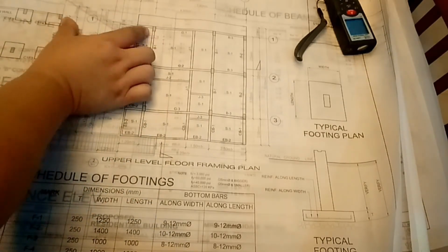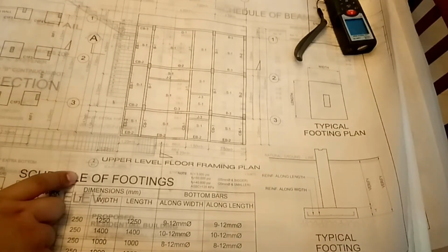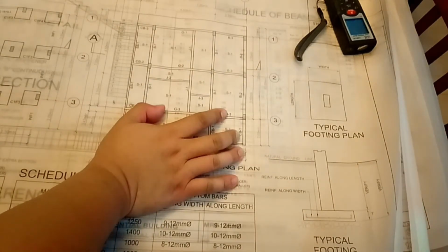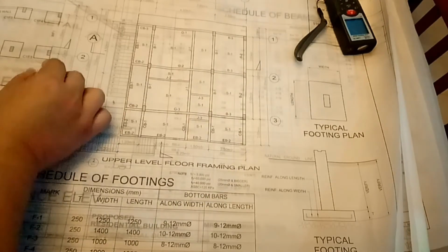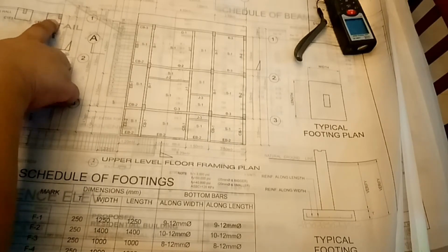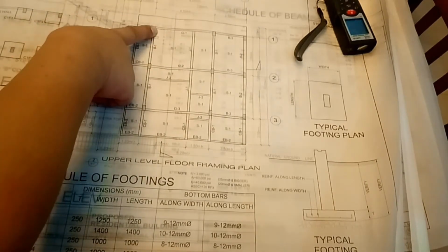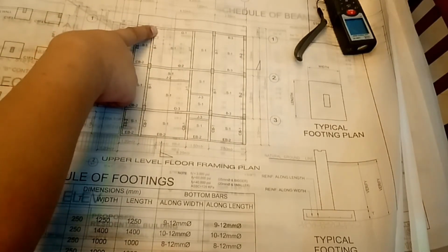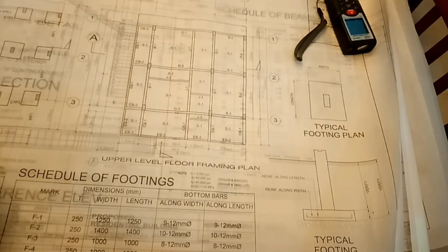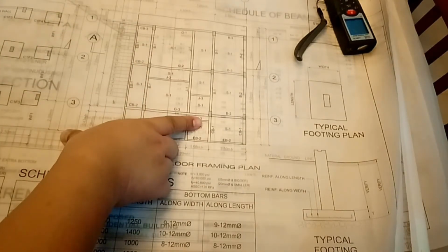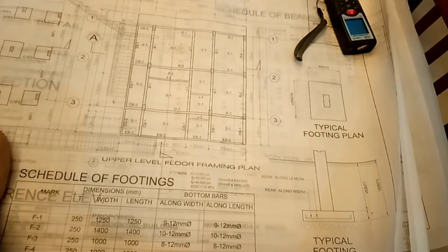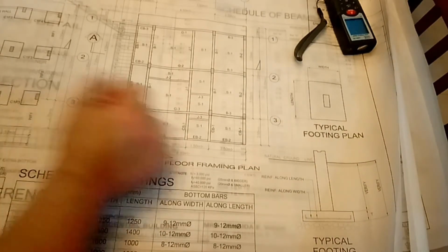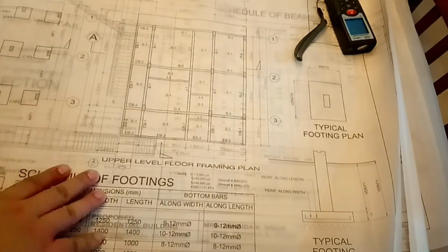So what's the significance of this during construction? So it means, class, that during construction, you'll be able to save on cost, especially on the forms. Because you just have to repeat the same size here up to the second floor. But if you're going to have different sizes in your ground and second floor, it means that you have to make 2 preparations for your forms. Okay.